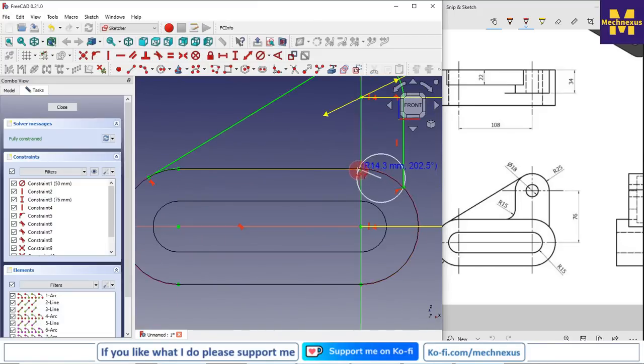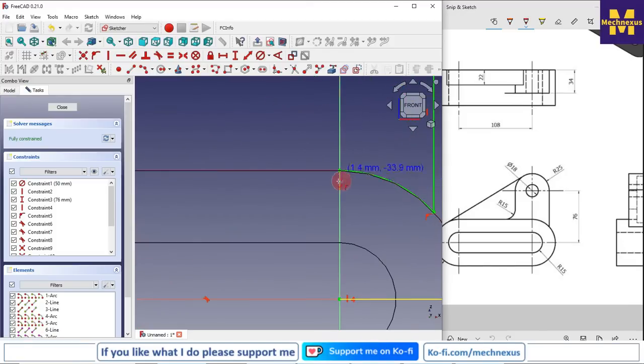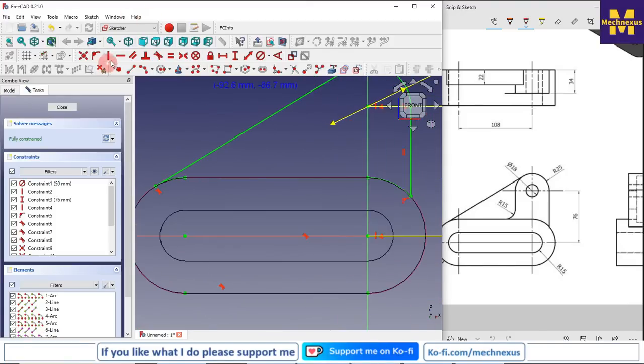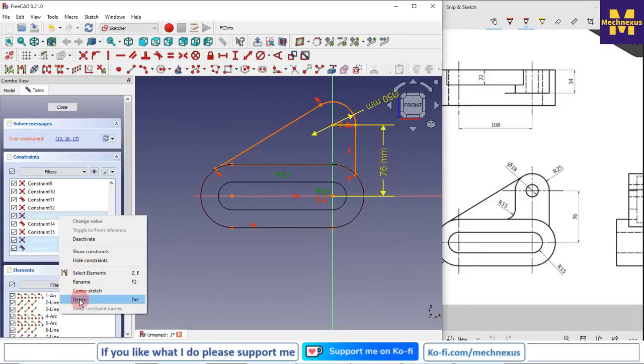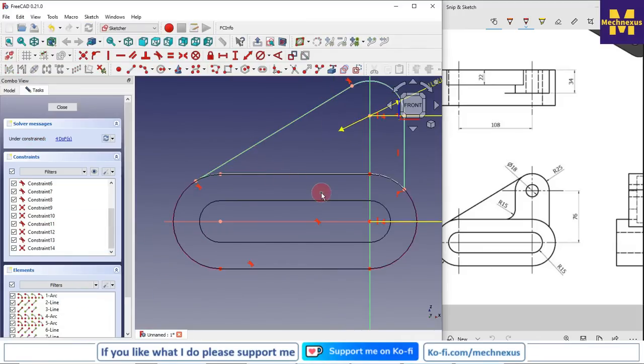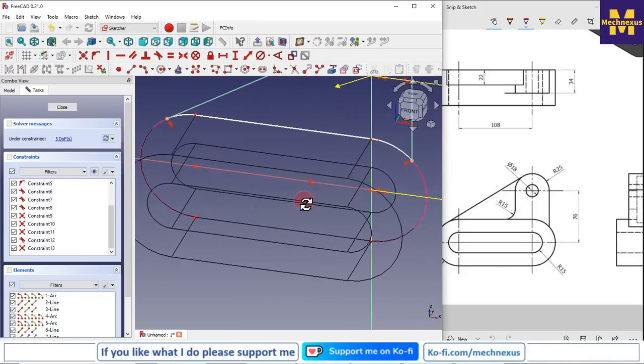Similarly I will create one arc here, and then I will close the profile. So here is a conflict, so I will delete it. Now let's see what is unconstrained. I will rotate it.